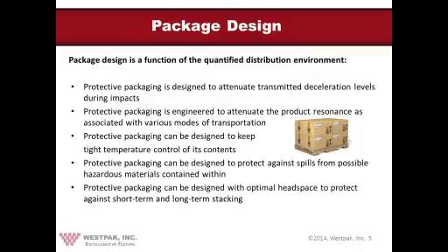And since we don't ride on trucks, we're not that familiar with it. It's not as intimate a hazard as impacts, because we see impacts, and that's a human phenomenon. People throw things, and that's what happens to a package. But we don't experience vibration levels on a truck. We experience them in a car, but whenever they get severe, we always slow down or fix the problem or something like that. A package can't do that. It's got to survive it, and that's the function of the cushion system.